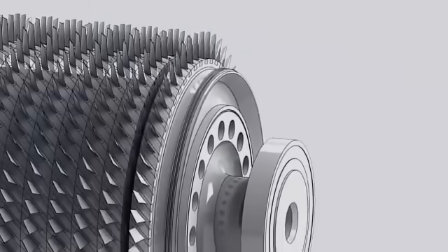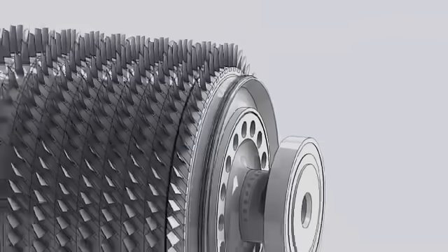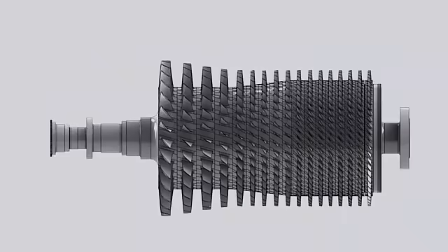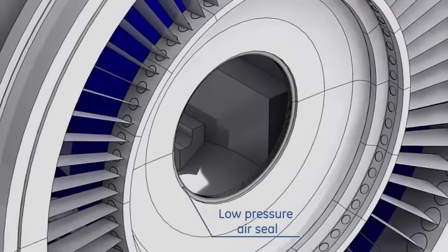The 17th stage blades are mounted on the wheel portion of the aft stub shaft, and they have only forward spacers. These spacers are placed to maintain the relative position between the rotor and the stator blades. Rotor blades are held in axial position by staking at both ends. Blue painted section inlet casing to prevent suction of contaminants into the compressor.